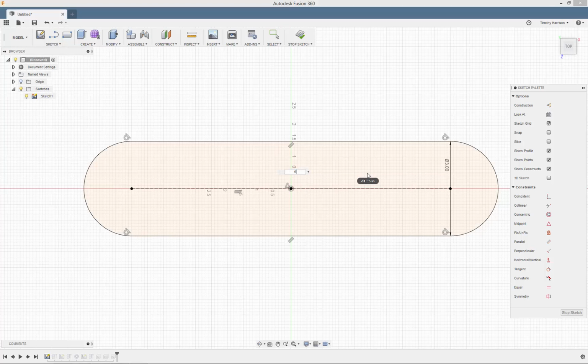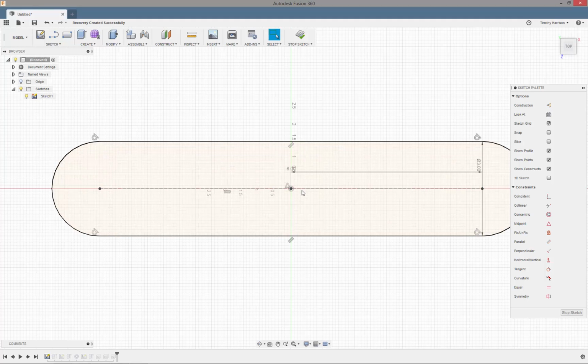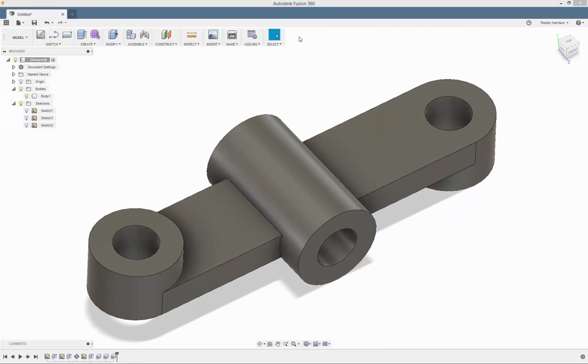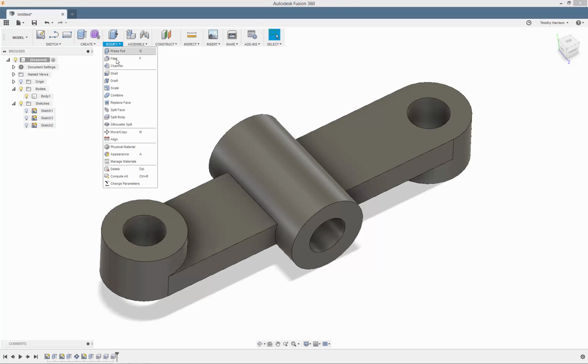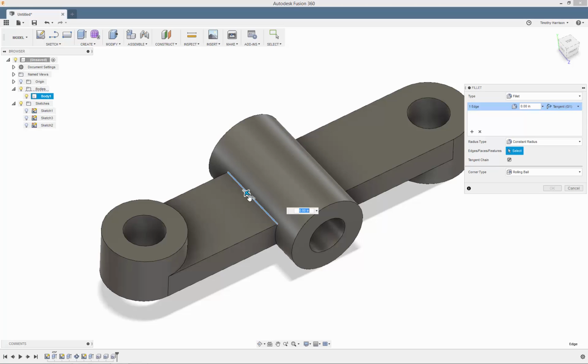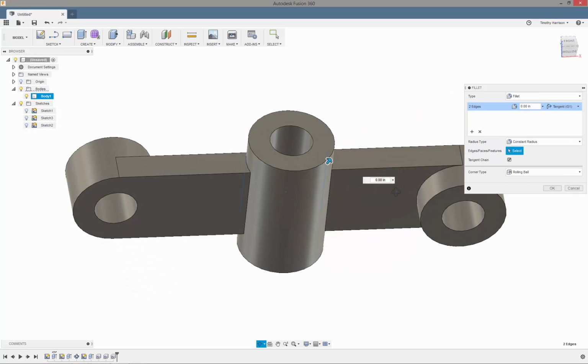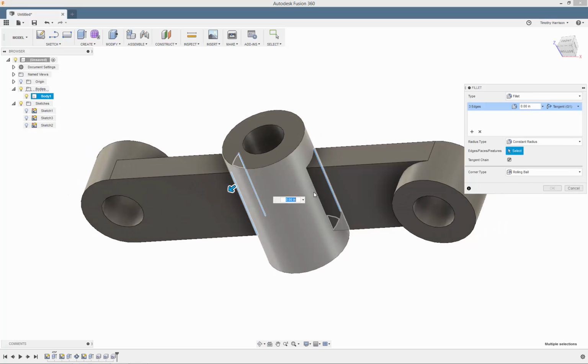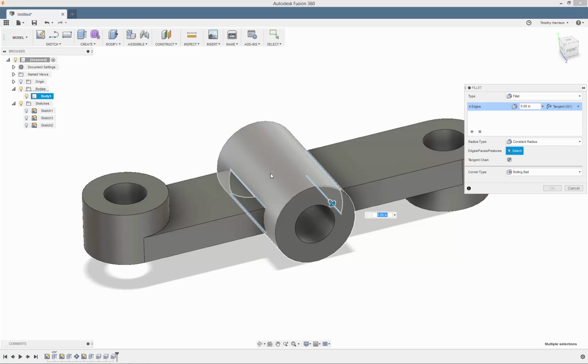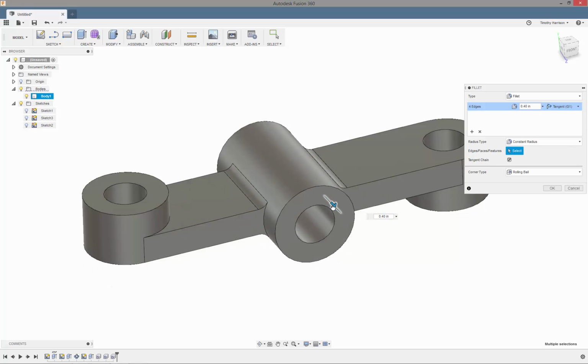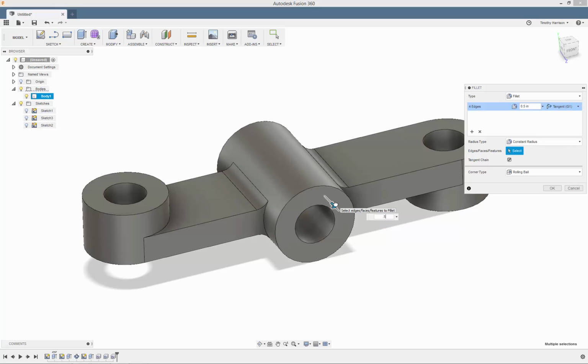We'll go ahead and change this now to 6 inches long. And notice that our part updates. We'll make one more modification here and we'll add a couple of fillets. We can select these edge lines. We'll select ones on the bottom here as well. When we drag this out, we can change the fillet size. We'll make this fillet a 1/2 inch, and we'll select OK.